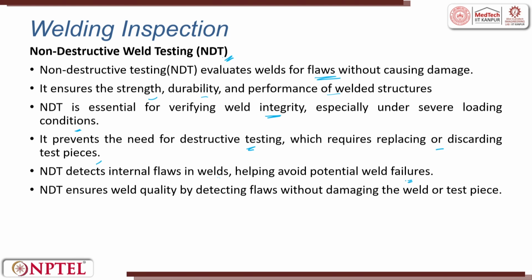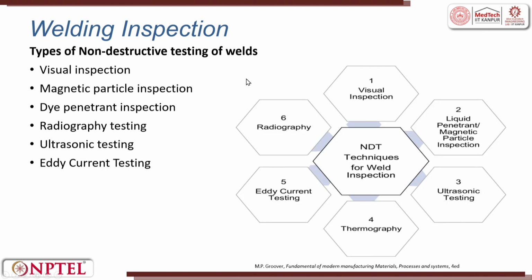Destructive testing is where you join, you destroy it and see, but that is costly. So, now we are trying to use a lot of non-destructive ways of inspecting. These are some of the non-destructive techniques which are used. Visual inspection can be thought of. Liquid penetrant is where you pour a liquid on a surface and then add a developer. Wherever there is an overflow of liquid, you can see very prominently that the development will not happen, while in the rest of the places it will happen.